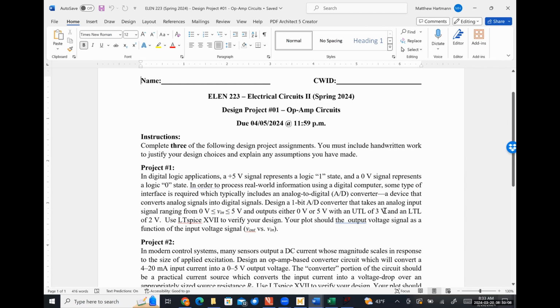So what would be a good choice for a reference voltage? Yeah, just something exactly in the middle to make the math really, really easy. I'm mentioning this explicitly to you guys because for whatever reason, students in previous quarters just did not seem to fundamentally understand that it needs to be between the trigger limits in order for it to work correctly. So I'm spelling it out to you here very explicitly, okay?